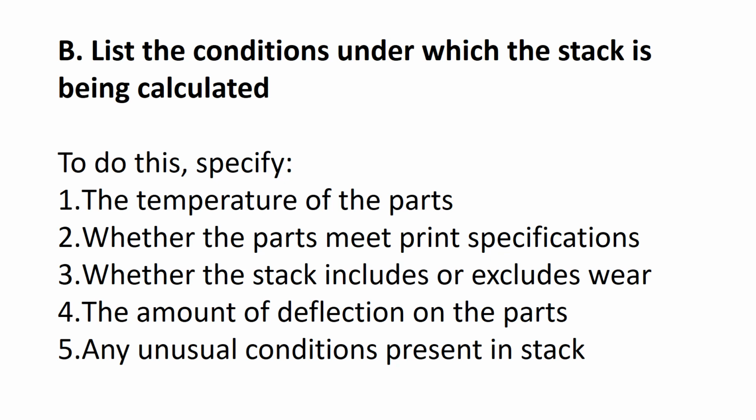And list the conditions under which the stack is being calculated: temperature and specifications, whether it includes or excludes any amount of deflection of the parts, and any other unusual conditions present in the stack.